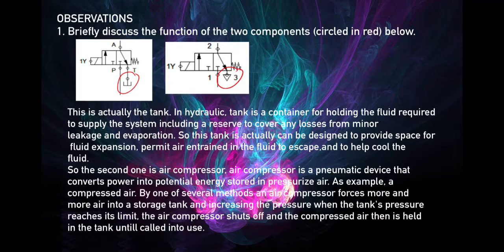This is actually the tank. In hydraulics, the tank is a container for holding the fluid required to supply the system, including a reserve to cover any losses from minor leakage and evaporation. So this tank can be designed to provide space for fluid expansion, permit air entering the fluid to escape, and help cool the fluid.